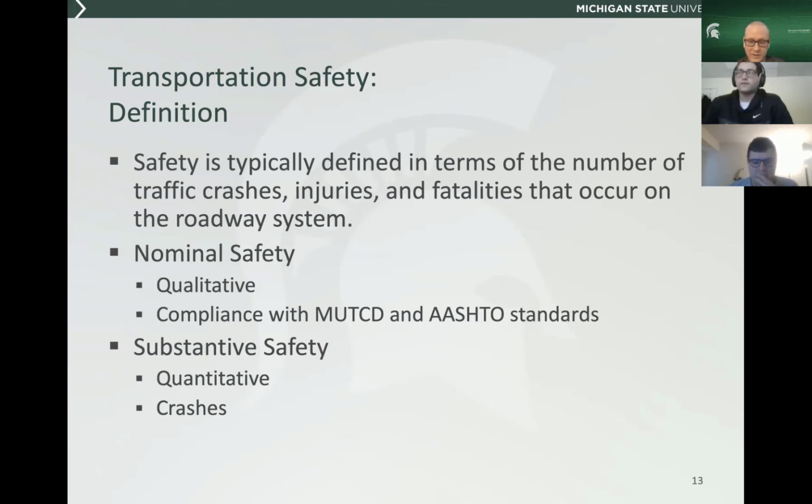And so in one case there, stopping sight distance, they had actually relaxed some of that guidance. For sag vertical curves, there really hasn't been any research that's shown that there's a specific safety concern, whether or not that minimum stopping sight distance is met. There's a variety of reasons for that we can get to later in the course, but that was actually removed from the controlling criteria.